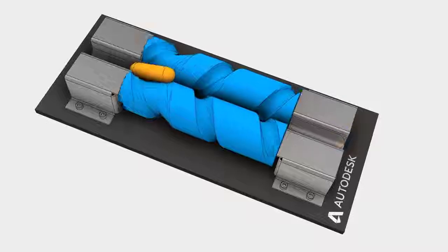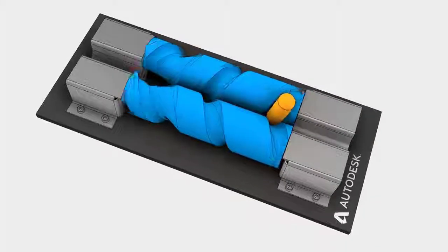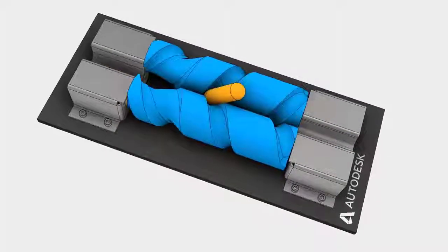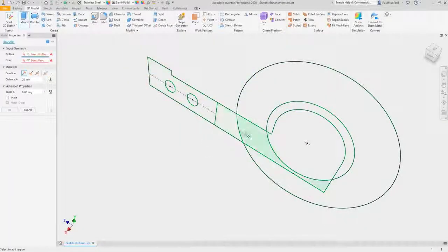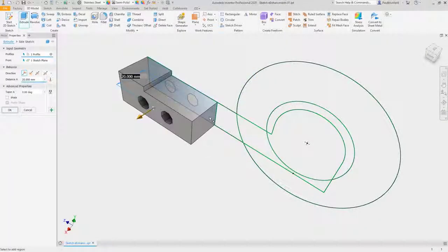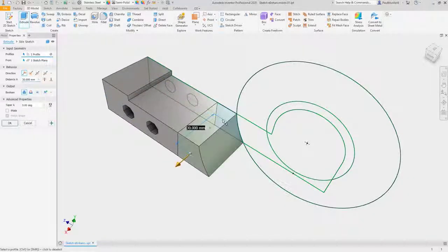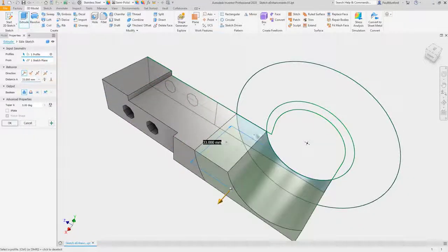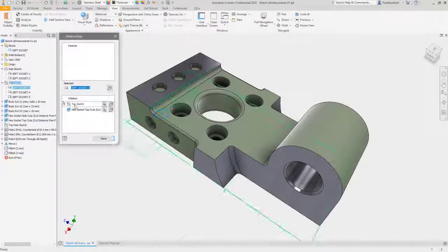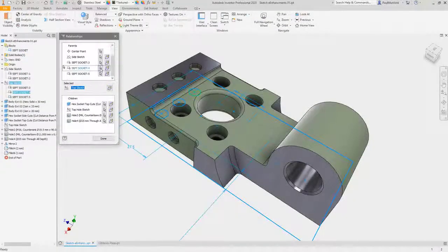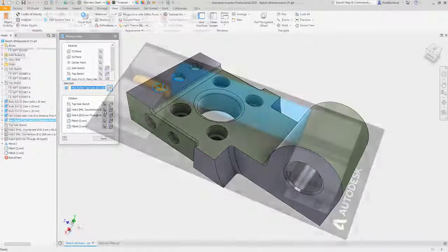Autodesk Inventor 2020 continues to deliver new functionality to your core design commands and workflows. In the part environment, get more options for identifying and selecting sketch geometry, including closed loops and regions formed by overlapping geometry or sketch blocks. In the Relationship dialog box, sketch blocks now display in relation to their consumed features.